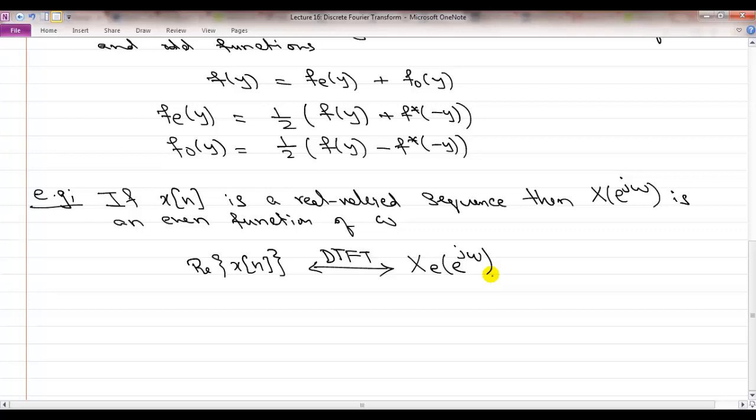Okay. So similar kinds of symmetry properties exist in the case of the discrete Fourier transform, but we have to be careful about the meaning of those properties. For example, a similar conclusion can be drawn that if you are given a real valued sequence, then the magnitude of your discrete Fourier transform will be even. So the whole discrete Fourier transform will be conjugate even, or even in the conjugate sense, which means if you just look at the magnitude, it will be even.